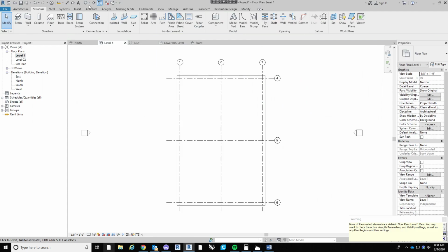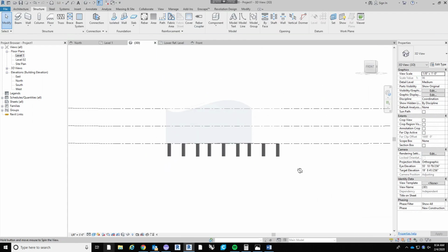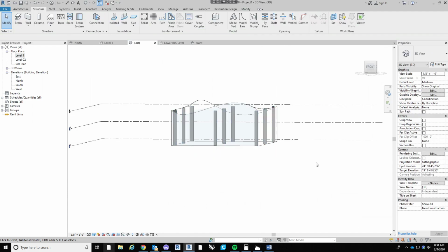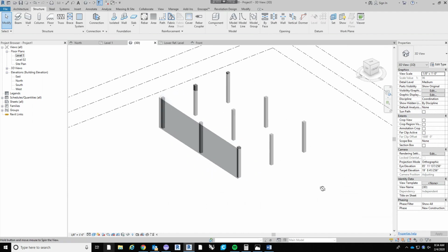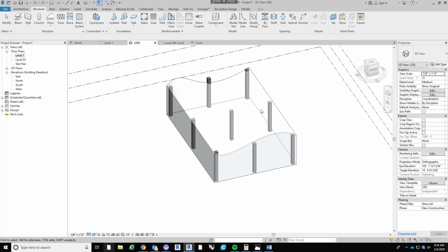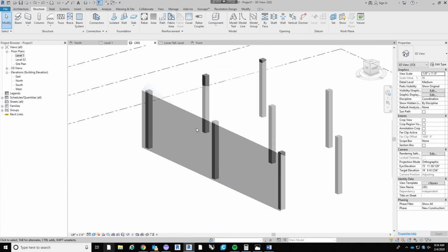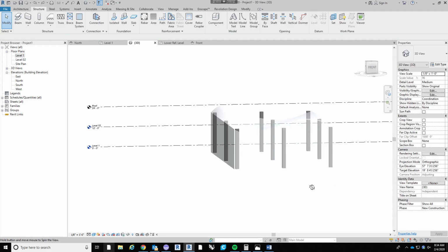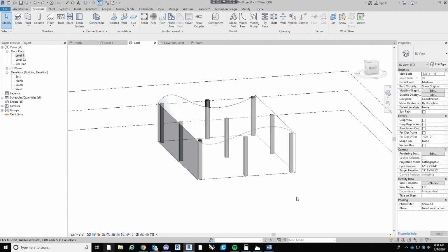And of course, none populate in the level because it's going to default to that -9 feet. Select all of them. Let's change that again to roof, 0, and we're good. Now we have structural columns tied to the grids. If we change these grids, it's going to shift the columns around. And we can go in and adjust these columns to any different height that they need, based on the double curved roof. Okay, let's keep that.